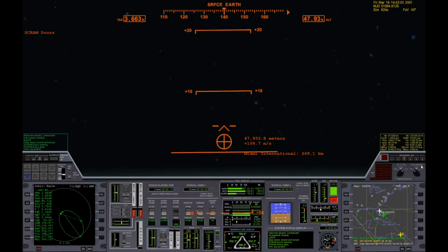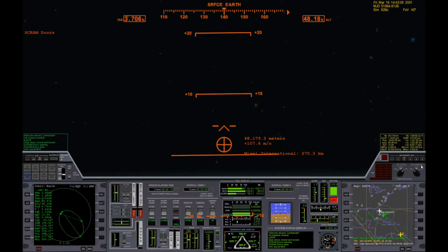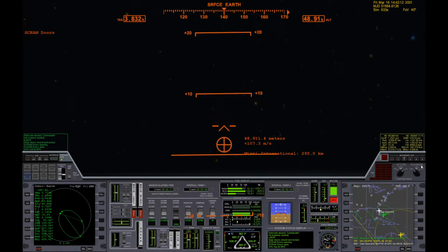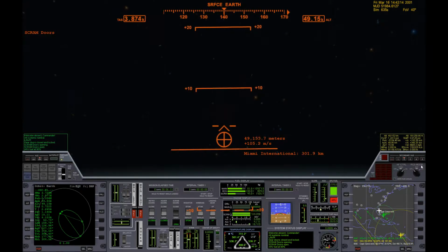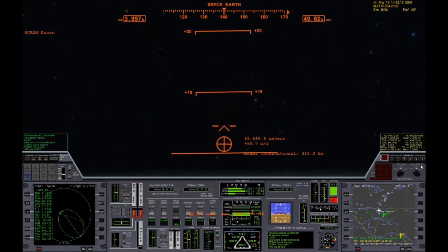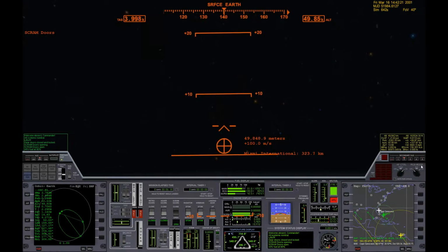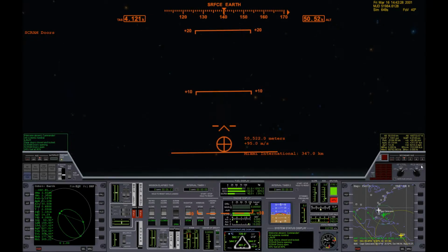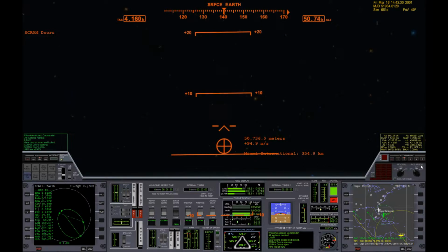Mach 11. Okay, we're starting to get high around 9 kilopascal, so what I'm going to do now is slowly work my dynamic pressure down to about 4 kilopascal at about Mach 20. Mach 12. You can press the insert and delete keys to adjust your elevator trim, which helps to maintain the plus 100 meters per second that you should maintain on the ascent.